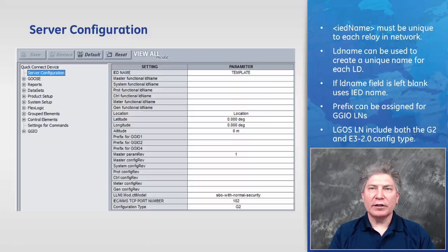Without going into a lot of details, the difference between the two is that there are some data objects in the LGOS logical node that are unique to each configuration type. So what we're doing is both types of LGOS logical nodes are included in the ICD files when the settings are being saved.